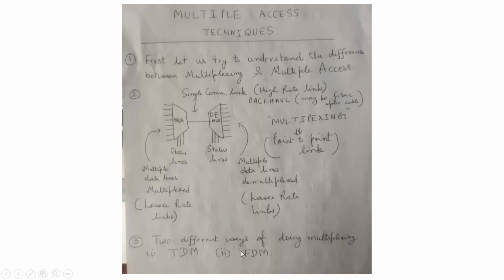But in frequency division multiplexing, every user will have a certain frequency allocated, and on that frequency the input will be superimposed, and every user will be allocated a different frequency. So when the signals are transmitted by different users, at the receiver side the frequencies on which they were superimposed can be tuned, and you can separate out the data lines based on frequency division multiplexing, right?